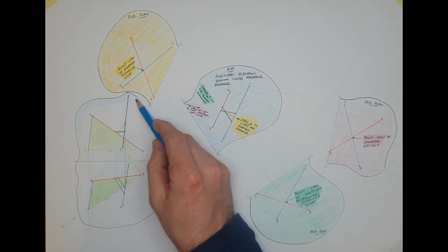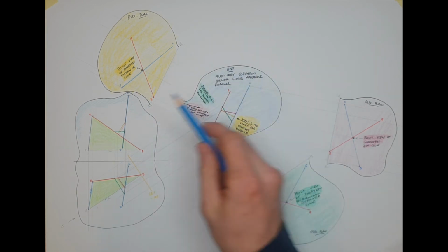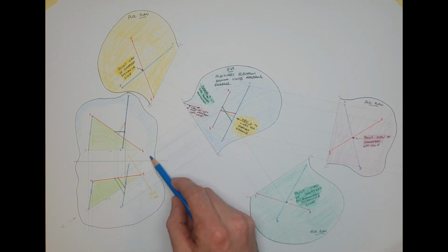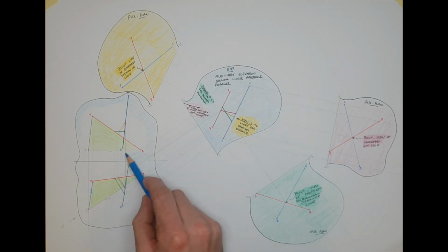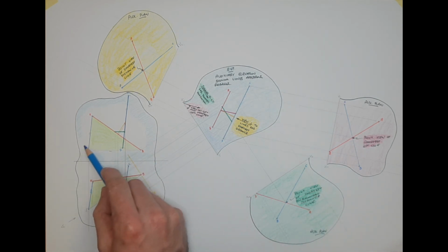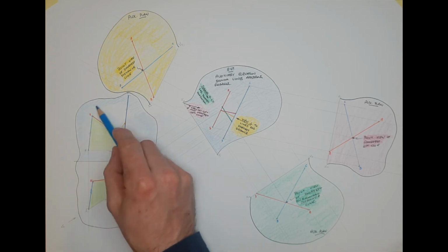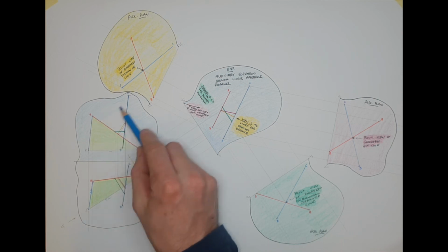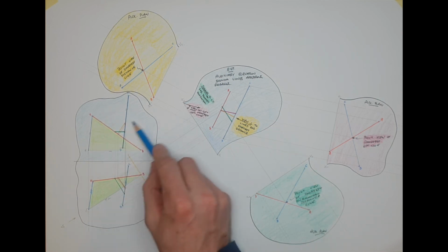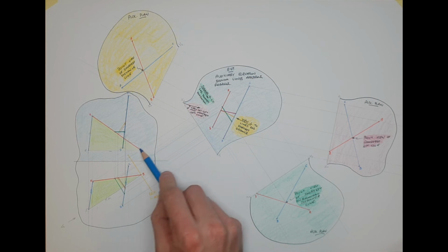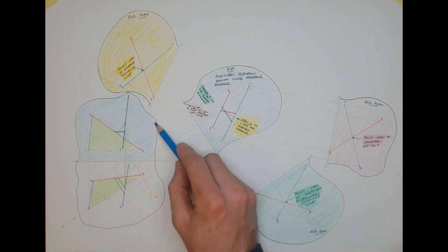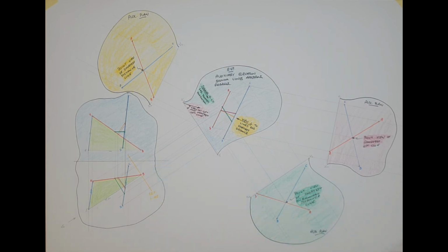The extra little notes I added in there up around here are all around the viewing directions and the resulting view that comes from that viewing direction. And I think that is probably, after the initial step here of creating this green plane, the next most important step on this drawing: knowing which direction to view or to project your second auxiliary. So that is definitely one of the key areas. So that's why my colour is in.